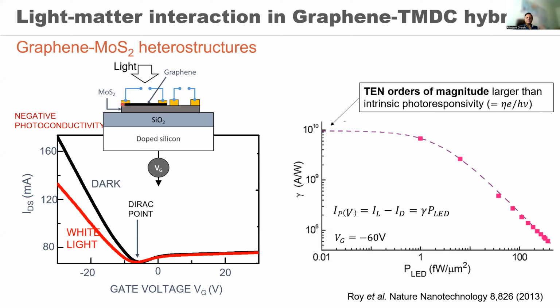You see, this is how we used two very interesting features of these materials. Graphene is a material which has high electrical mobility and very little light absorption, whereas molybdenum disulfide has very little electrical mobility, but very good light absorption. By putting them together, we essentially created a new structure that can leverage the good things of both.